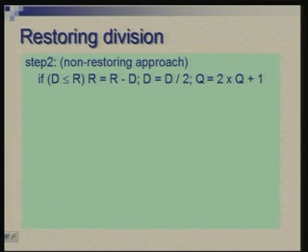this step which was there, where I am now getting back to the first form of the algorithm, where after the basic algorithm we had introduced the shifting operations. Okay. So, we were comparing d and r, and accordingly we were subtracting. So, this is actually called the non-restoring approach. We first check and then subtract. An alternative is that we carry out subtraction in anticipation, and if we have made a mistake, then we restore or we make a correction. So, that is called the restoring division.